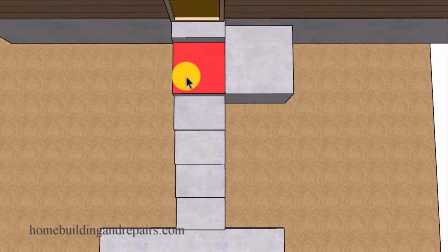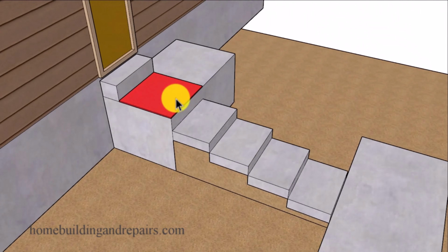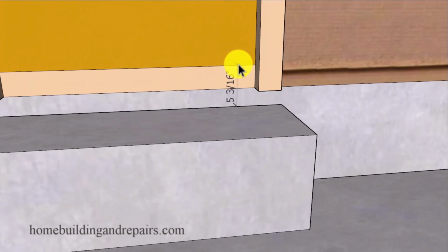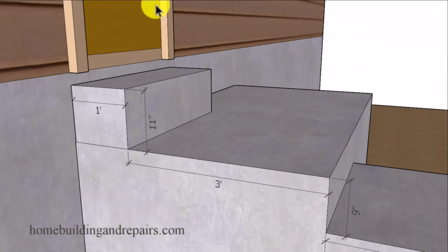So keep that in mind if you're dealing with a situation like this. As long as you have a landing, something that your local building department will approve as a landing, that is usually going to be the width of the stairway in depth. So I believe here we have a 3-foot wide stairway and we have a 3-foot depth. Except we have a few riser variations where, coming out of the house or the top of the floor inside the house, we have about 5 3/16 of an inch for our riser, and this usually won't be a problem if the door swings into the house and not over the steps. And I do have other videos on that at our website in the building code area.